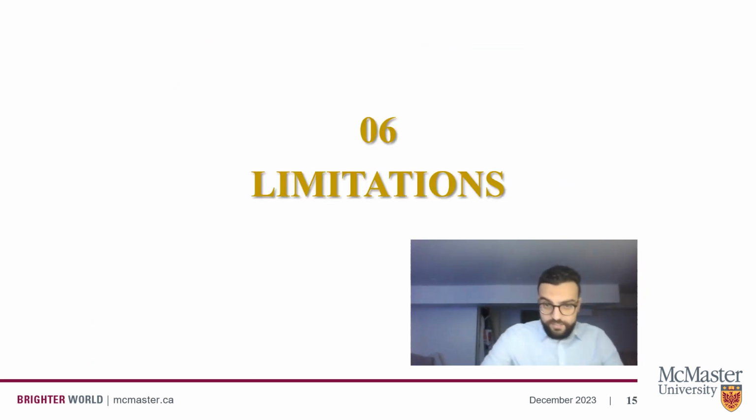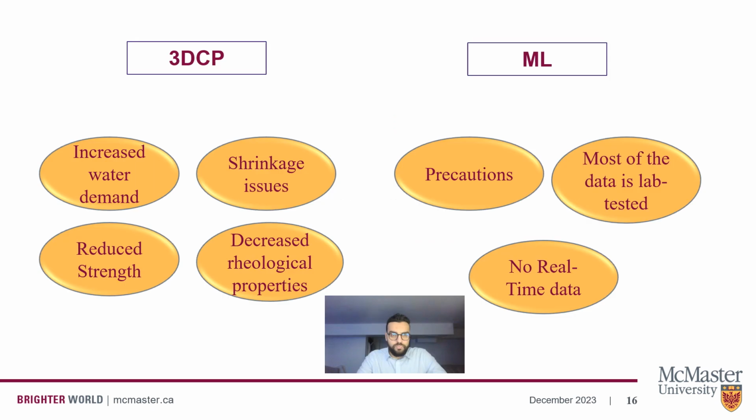So this study presented a list of limitations, and we are trying to summarize them into this slide. So for 3D concrete printing, we discovered that adding this kind of recycled particles can increase the water demand, which can lead to some shrinkage issues, and this also can lead to reduced long-term strength and a decreased, to some extent, impact on the rheological properties and the viscosity of the mix.